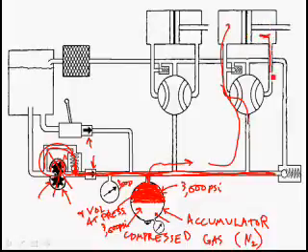Of course, the other side of the actuator, fluid would go around and back to the reservoir. So for a little while, just like a battery in a 172, this would provide us with a small amount of power for the system for a short period of time. So that's one of the three things that a hydraulic accumulator can do: it provides emergency hydraulic power.